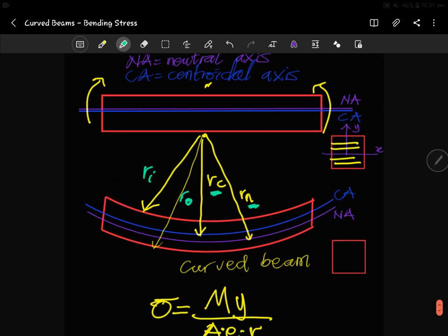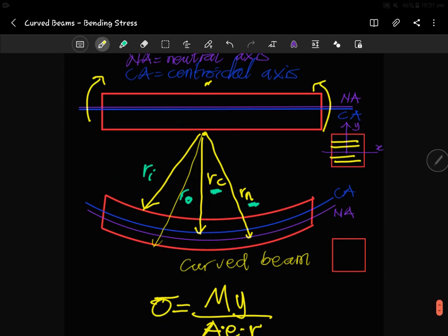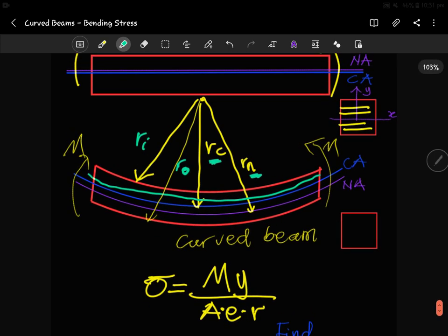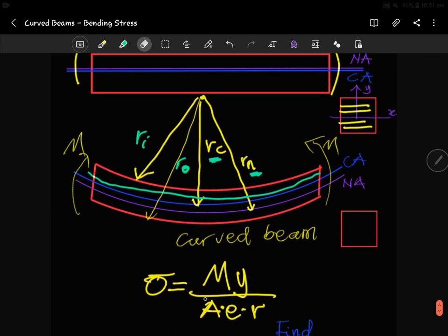So for this particular beam, if I apply a moment or bending moment on it, and I pick a particular position, let's say about here, to see what's happening. Because I have no force, the only stress within this particular section will be as a result of the moment, right? And for that we write it in a particular way for the curved beam, which we write this way.